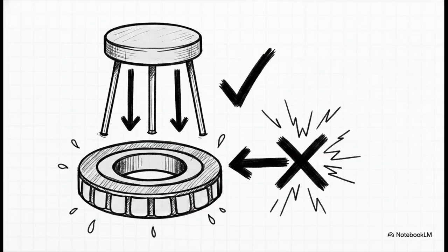Now, that brings us to the thrust ball bearing. These are flat, washer-style bearings designed to take purely axial force. They are amazing for lazy Susan turntables or heavy bar stool swivels. But here is the absolute kicker. If you apply any radial force to a thrust bearing, the balls will literally slide instead of roll, and it'll destroy itself in no time. Plus, under really low loads, they actually require continuous lubrication just to prevent the internal cage from skidding.